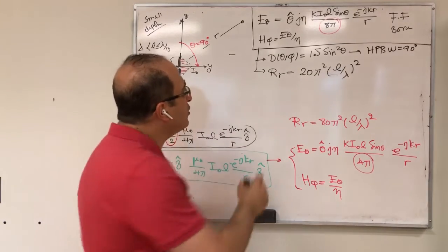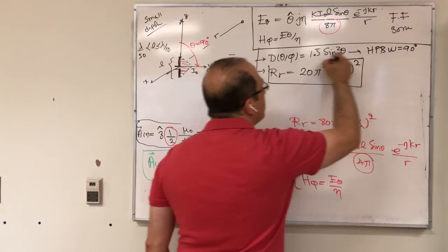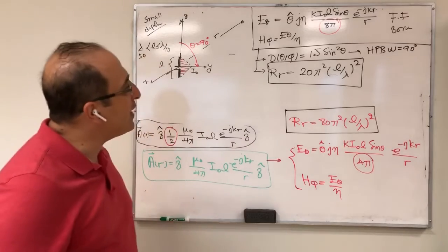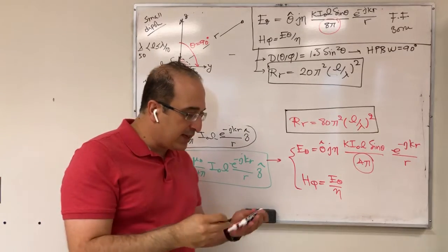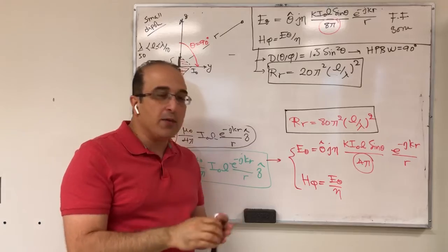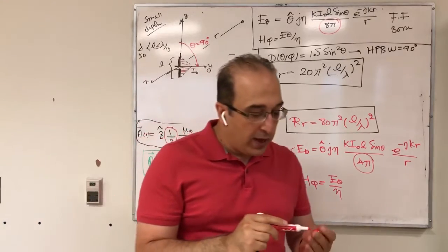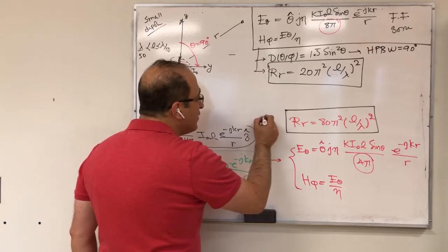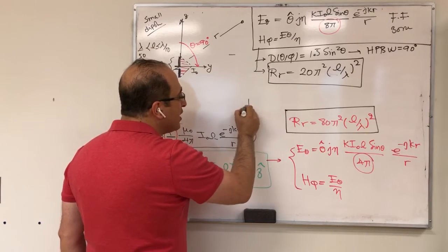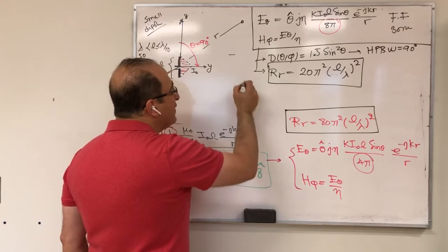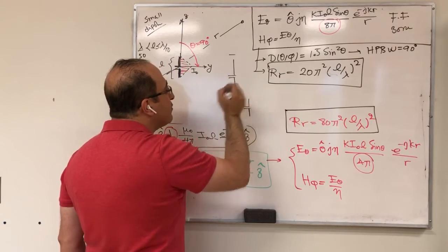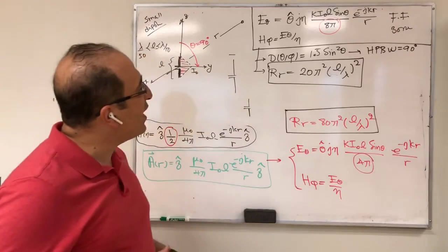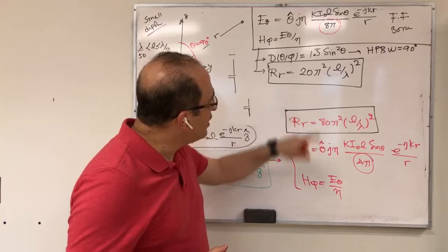Now, at this point, we always have some confusion. When you look at that, you might see something counterintuitive. If this is, for example, the size of this antenna, and the small dipole antenna is of larger size, you see that the radiation resistance is in fact smaller than this.